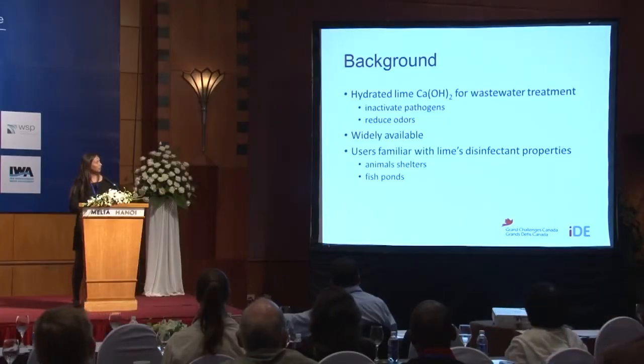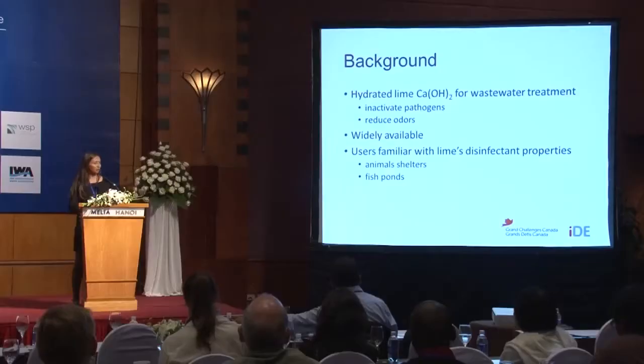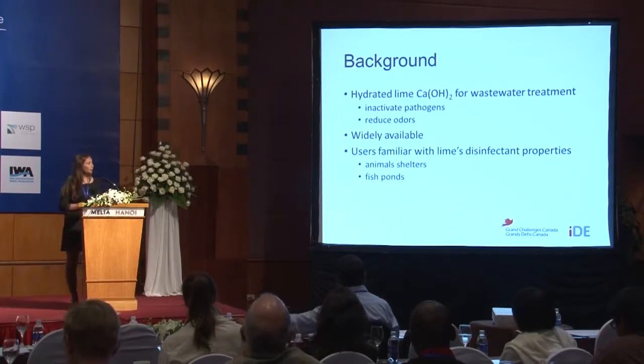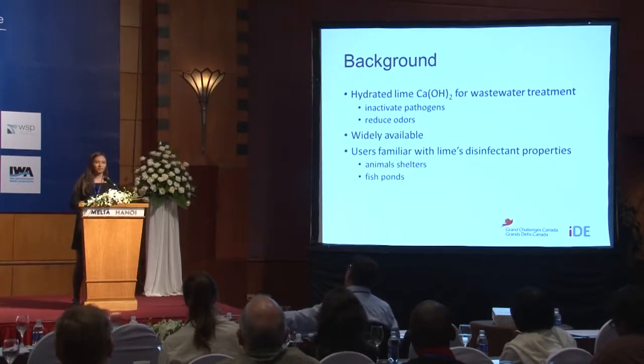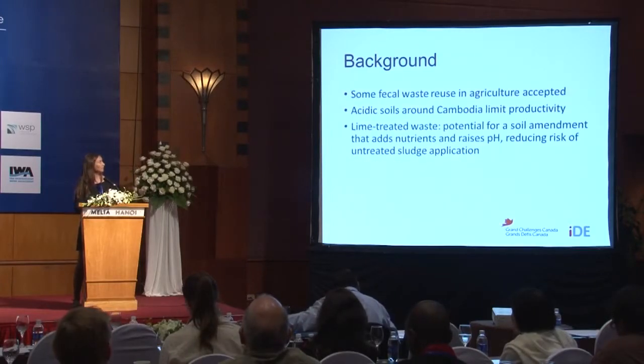So the reason to use hydrated lime, CaOH2, for wastewater treatment and sludge treatment is basically it inactivates pathogens and reduces odors. These are the 2 key characteristics. It's quite widely available, at a quite low price. In Cambodia, a lot of users are familiar with the fact that it does have disinfecting properties. It's quite often used for disinfecting animal shelters and for disinfecting fish ponds as well.